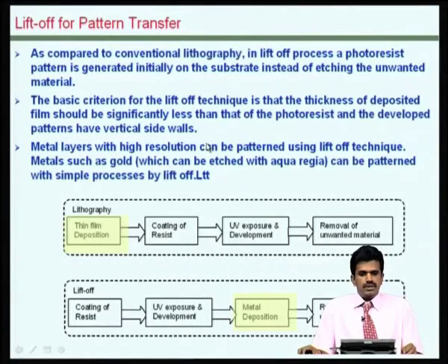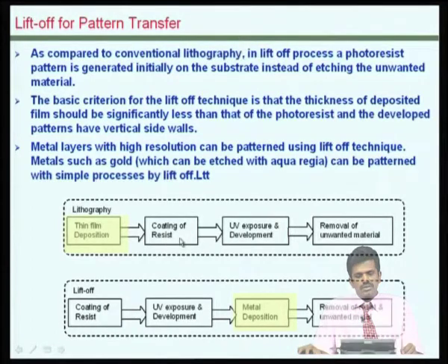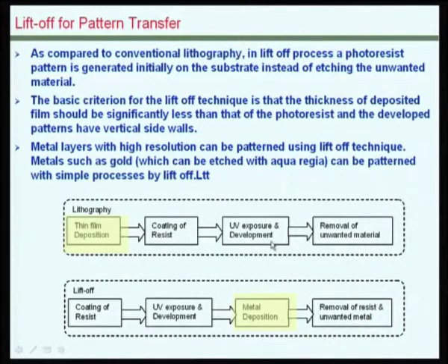Liftoff technique is another pattern transfer approach which is somewhat similar yet different from the lithography approach. In a standard lithography approach, what we do is first deposit the thin film and then coat it with the resist and then expose and develop, and after that you remove the unwanted material.